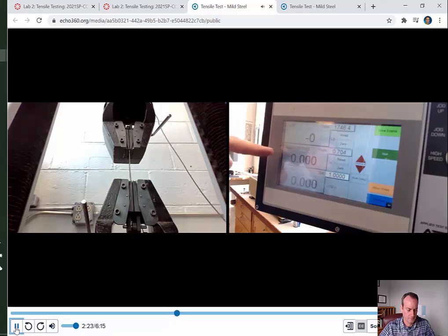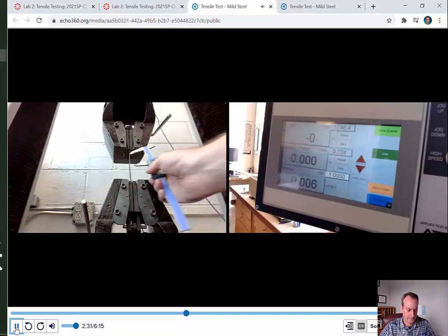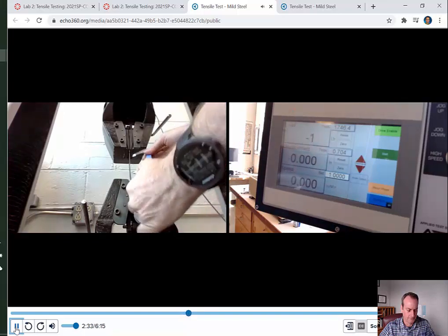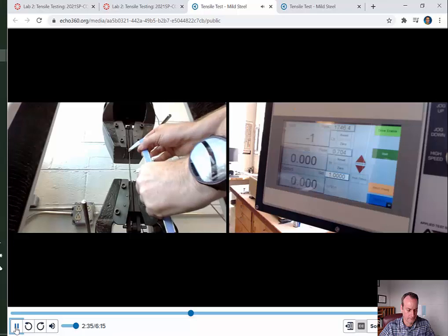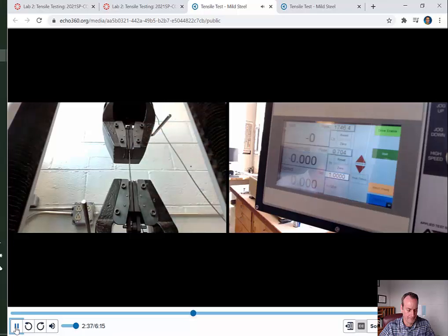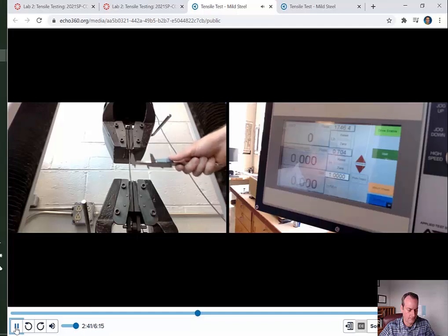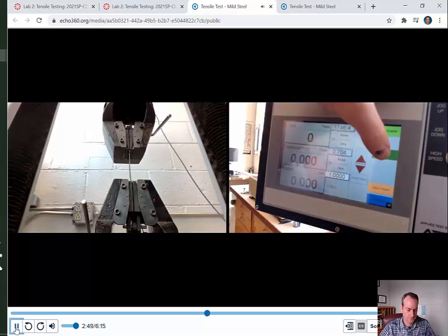Well, actually, you can calculate your strain, which is the displacement divided by your original length, which I forgot to measure, right? So if I put the calipers on here, I don't know if I can still do it in here. I can already tell you that the initial length is 3 inches. So the original length, the distance between that thinner section that is going to be under strain, is 3 inches. So let's go ahead and get started. And I'm going to hit start.